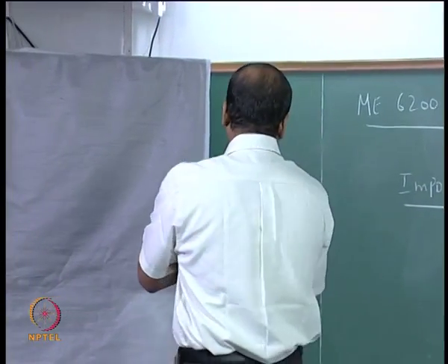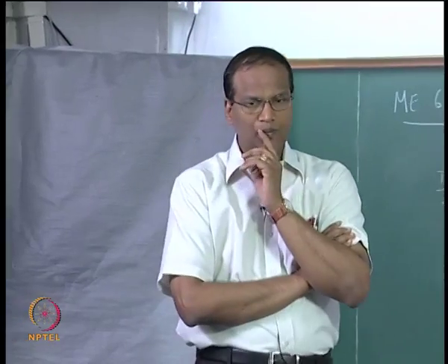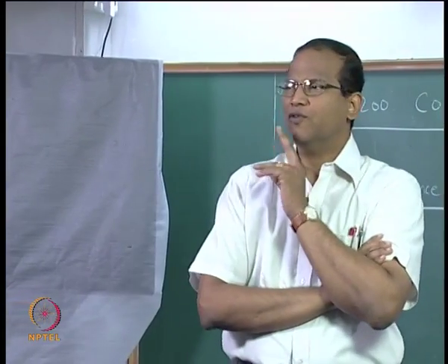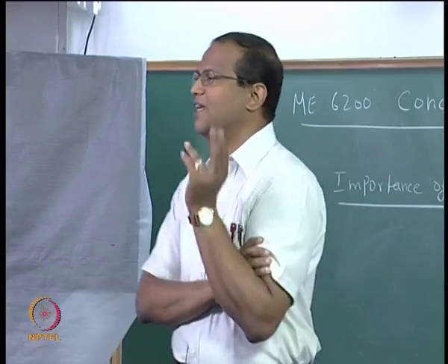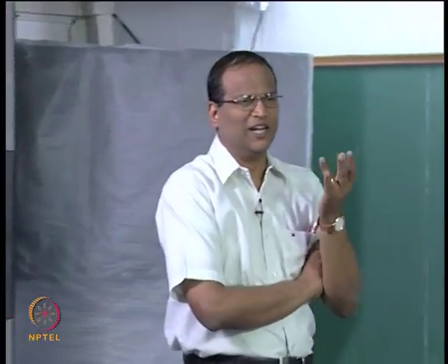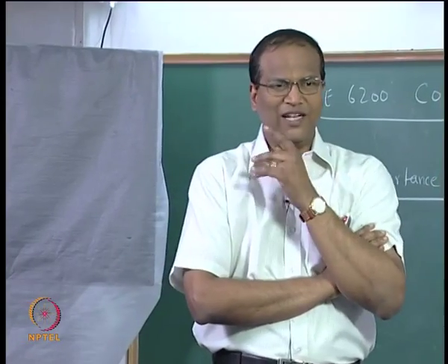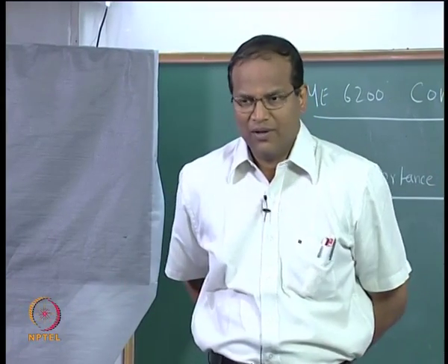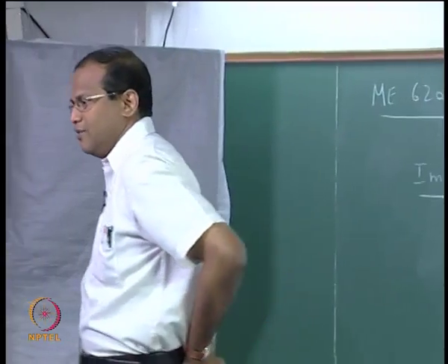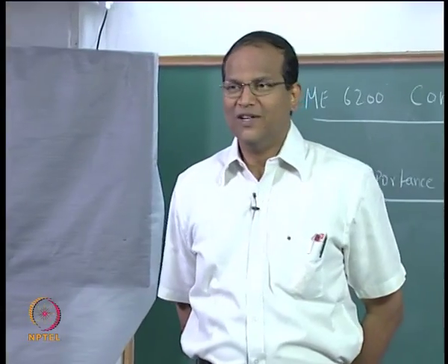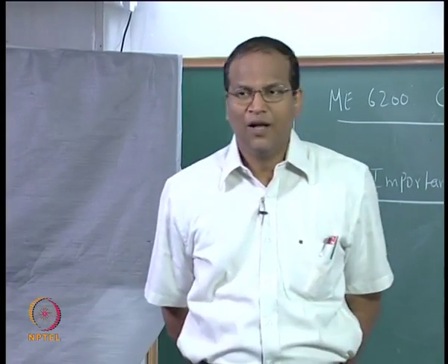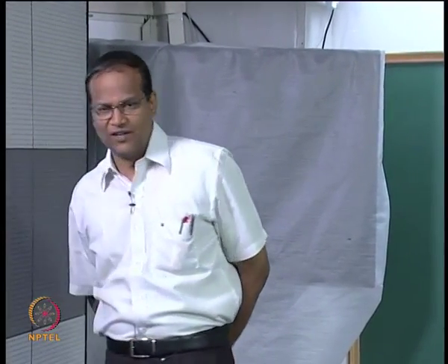Now in this class we look at the importance of thermal radiation, why thermal radiation is important. Most people have a general feeling that thermal radiation is important only when the temperatures are high, right. Generally when the temperatures are low we say radiation can be neglected, an argument put forward by many people who are not inclined to include radiation in their analysis. So we will take a simple example and see whether this assumption of neglecting radiation in a heat transfer analysis is justified.